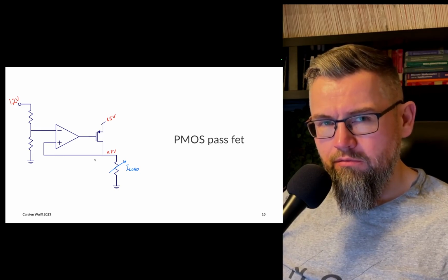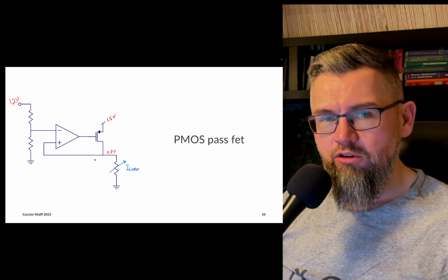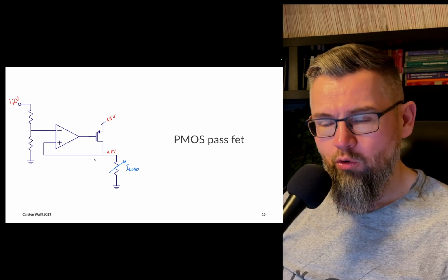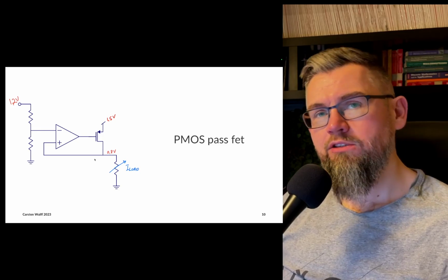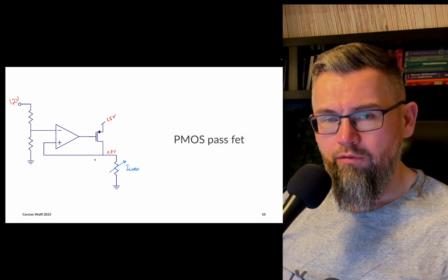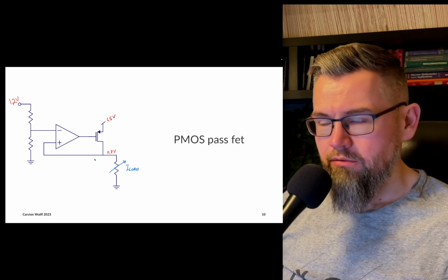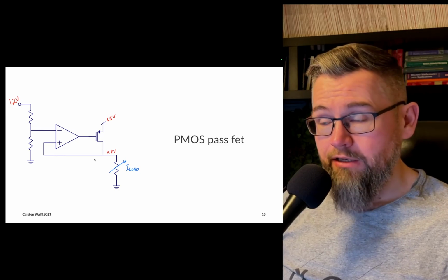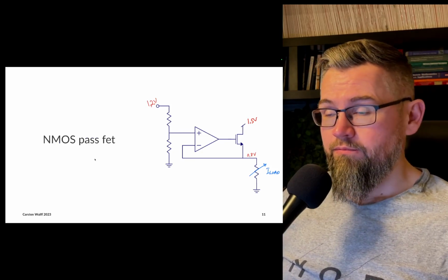The mobility of PMOS, the mobility of holes, is a bit slower than NMOS, which means that you need a larger device to get the same current for a certain overdrive voltage. So it would be better from a size perspective if we could use an NMOS.